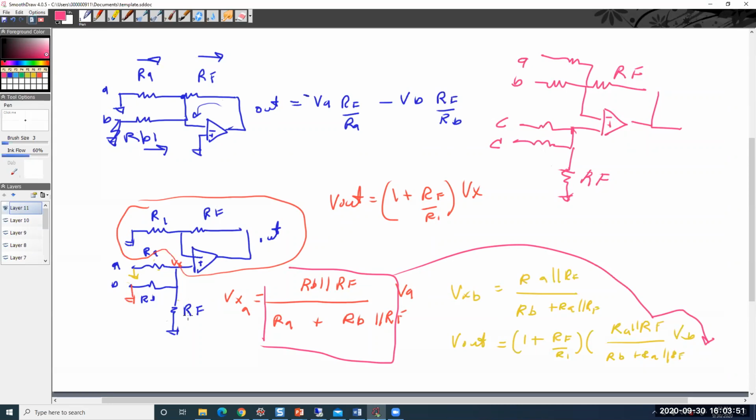So the important part, again, what I'm about to talk about, is that the gains balance. But when I'm designing things, I try to use as many of the same part as I can. So if RF is going to be 100 kilo ohms here, then I want 100 kilo ohms here rather than some other value that I have to keep track of, okay?